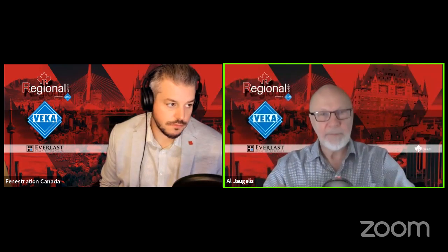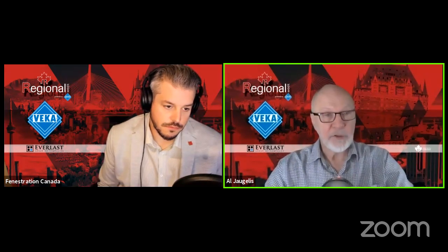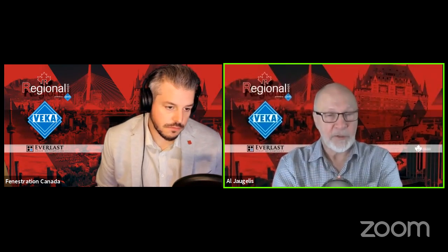It's a combination of assembly of individual products. So to get the performance of the combination assembly, you have to test the whole assembly. Doesn't mean you have to test an assembly of 4 of them together. You could test 2 of them together. What you want to know is when you join 2 or more windows together to make a larger window, you want to know that the joints between them are airtight and watertight to the same level as the individual units. Or if the joint makes it less airtight or watertight, then the performance of that joint becomes the new performance level of that assembled window.